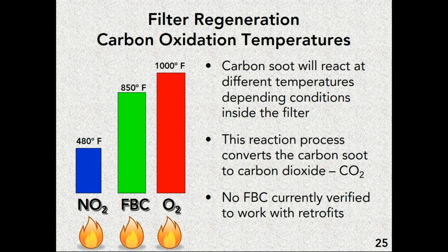The basic problem we have here, though, is that carbon requires a specific minimum temperature in order to combust. If you have nothing but oxygen, let's say we just had a bunch of chunks of charcoal and we put it in a Weber or some crucible that we can burn it, we would have to get that charcoal up to 1,000 degrees before it would actually stably burn on its own. Now, why is that a problem? Because most engines cannot get to 1,000 degrees in the exhaust. If they did, they would mostly burn up. So that's not going to be doable for most engine duty cycles. In fact, it's very few that will get to that temperature.